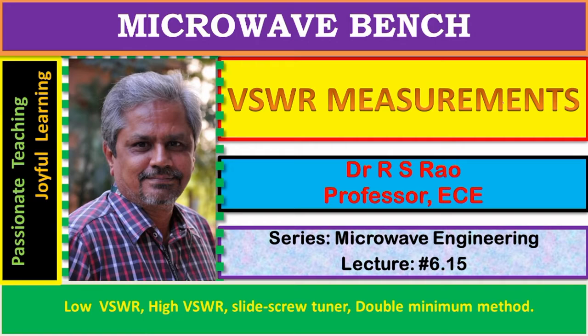By definition, SWR is the ratio of maximum voltage to minimum voltage, or the ratio of maximum current to minimum current in the standing wave pattern over a lossless line. Notice SWR is defined with respect to a lossless line. It is relevant only in the case of lossless lines. Its value ranges from 1 to infinity.